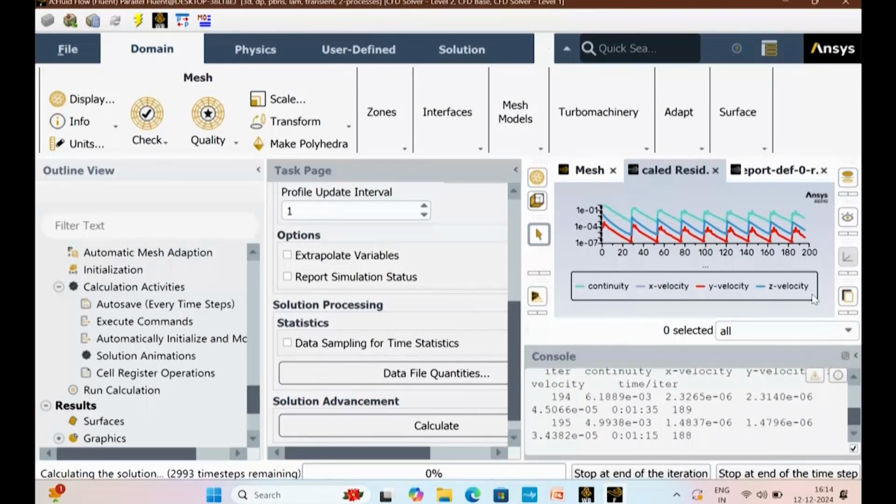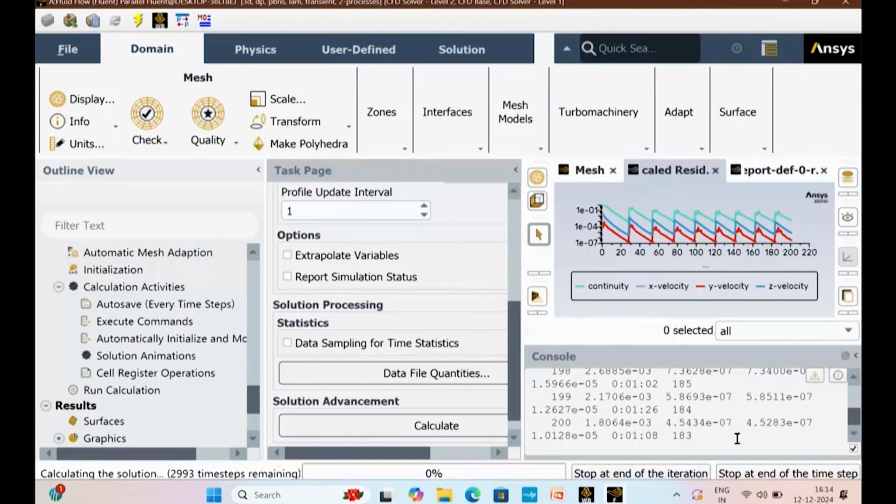So it is converging within 20 or 21 iterations, right? Yes. So it is better to prescribe the maximum iterations per time step to a higher value, even if it will not take all of them, it's okay. But if you prescribe 10 to the power minus 6, then I think it will go up to at least 60 to 80.